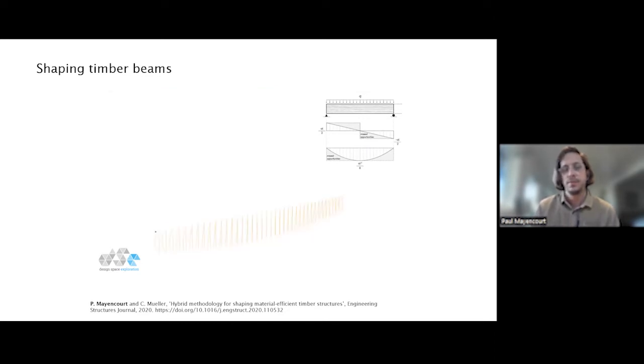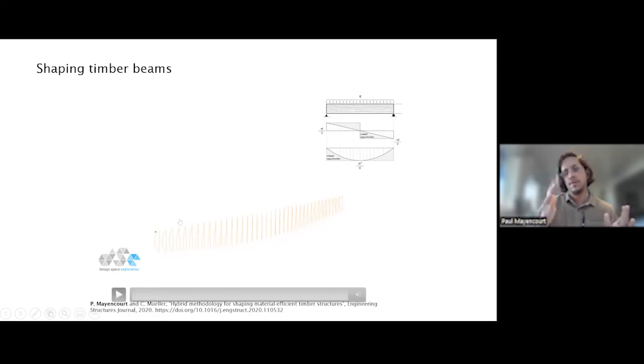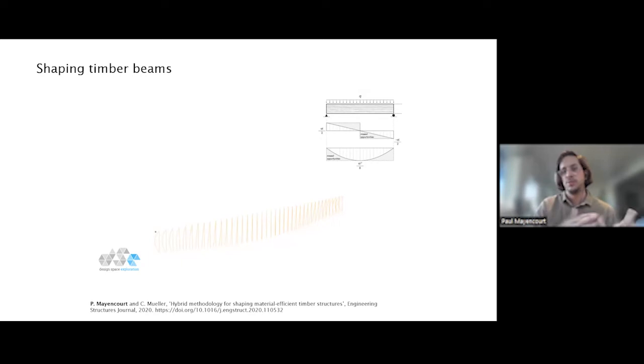And some of the work that I have in the citation here has been creating the mechanical models to express the behavior of these elements that are shaped. There was some knowledge on how these shaped elements behave, but not combined into a coherent model. So some of my work has been on the timber mechanics and shaping optimization in the background of this methodology here that you see, and it outputs the shear stress and bending stress distribution everywhere in the beam in a closed-loop, or analytical, equation.